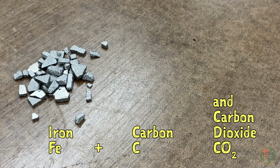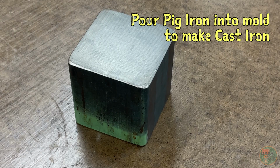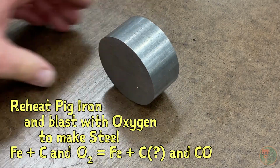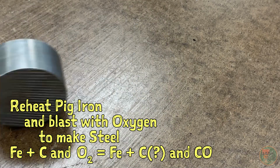This pig iron, as they call it, can be poured into a mold and then it becomes cast iron. Or it can be reheated and blown full of oxygen. The oxygen reacts with the carbon in the iron to produce carbon monoxide and leaves just the iron behind. Using a similar process, a precise amount of carbon can be added back into the iron to achieve the desired concentration. And now you have steel.